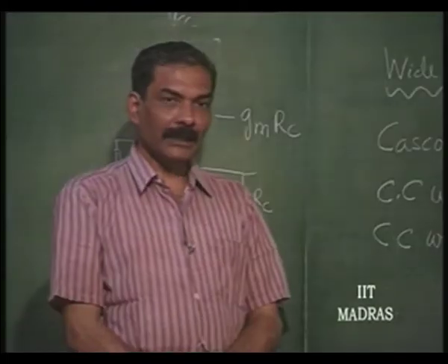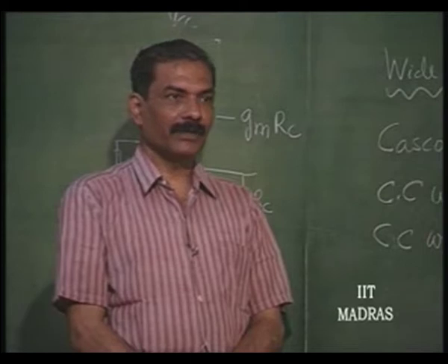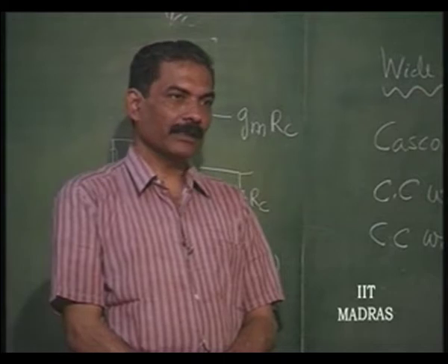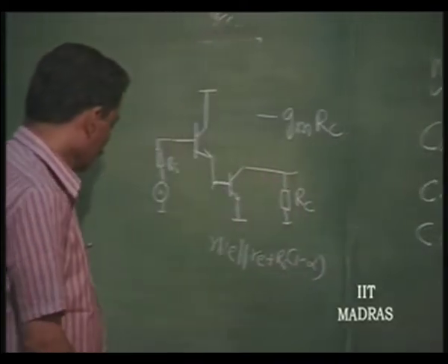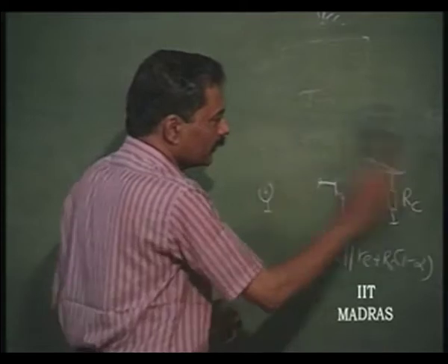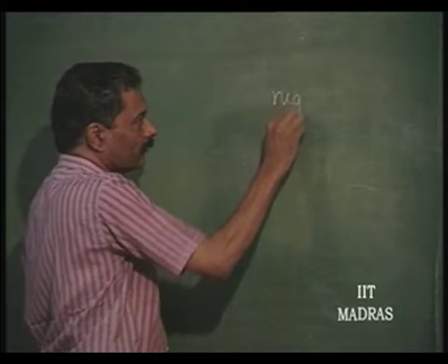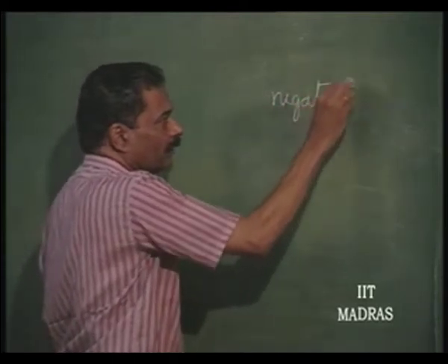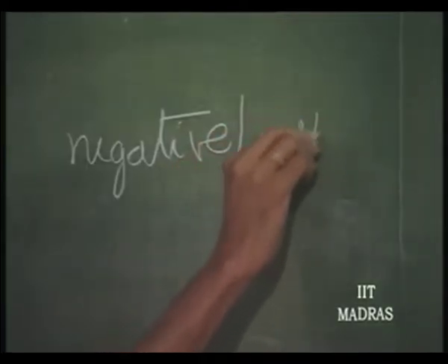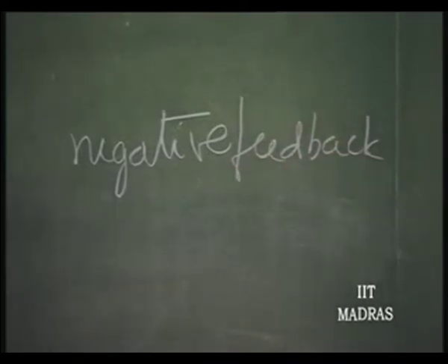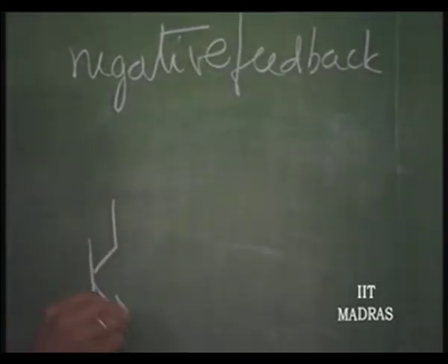We have, apart from this, negative feedback amplifier stages with local feedback, used for wideband application. This I have already discussed earlier. These stages, which are negative feedback stages, necessarily must have simple poles, first order or second order poles, so that they do not go into oscillation. So, such structures are the following.